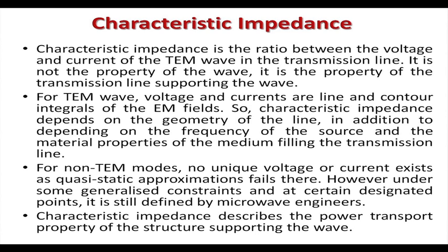Antenna has input impedance, that is a separate concept, but it is not characteristic impedance. The wave that antenna radiates, we calculate is wave impedance. But for a line, we say characteristic impedance. For a TEM wave, as we have seen, the fields are quasi-static.